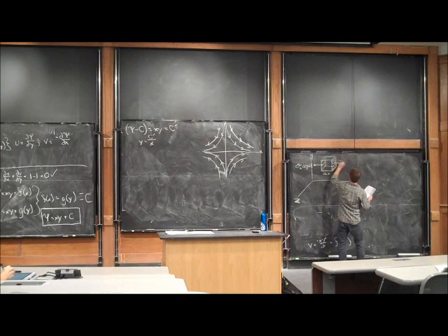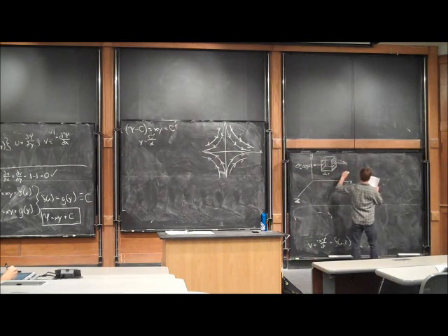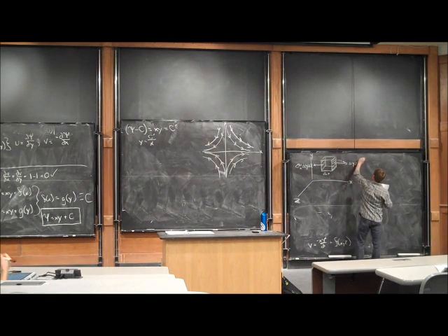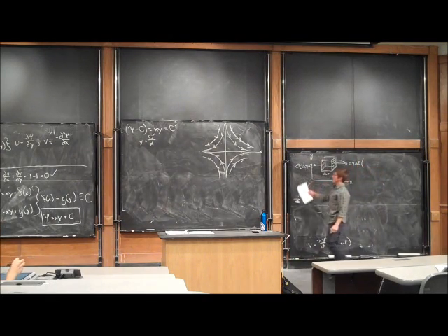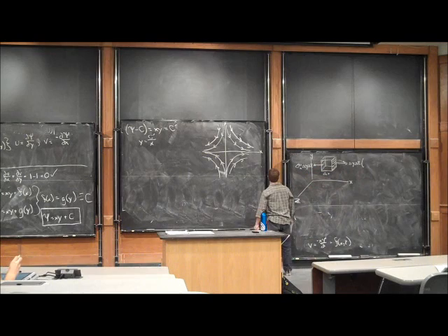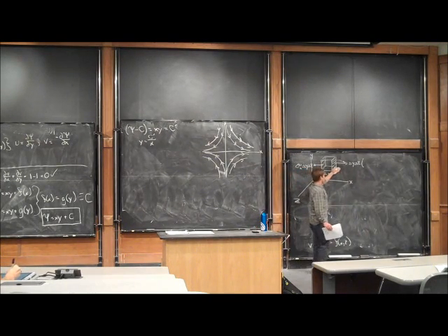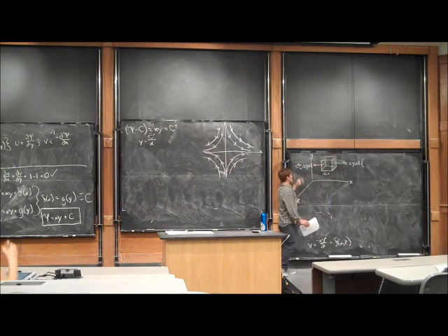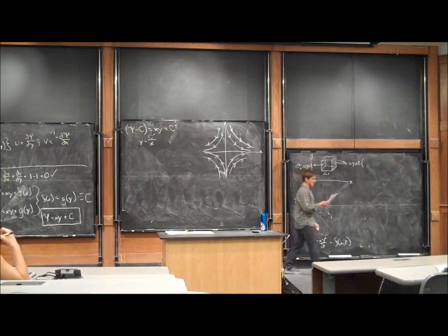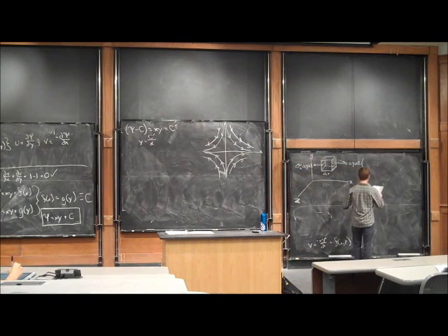Similarly, on this side of the element, we're going to have the same surface area times a different stress, because much like the velocity field, which will have a different value on one side of the cube than the other side of the cube, the stress will have a different value on both sides of the cube as well.